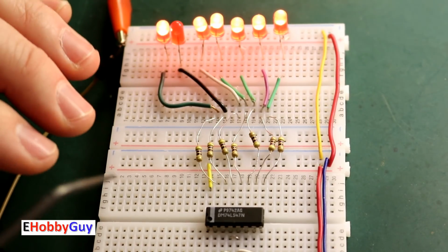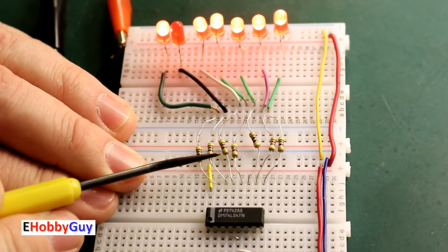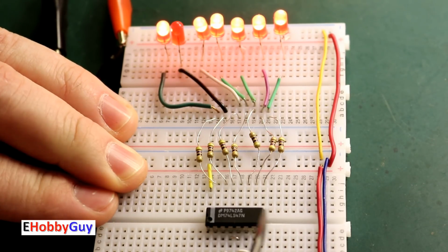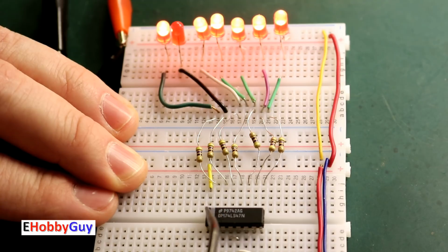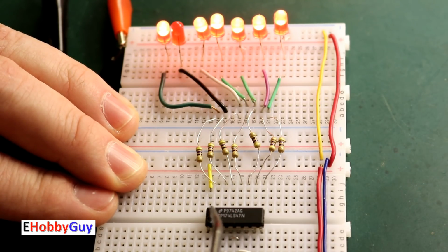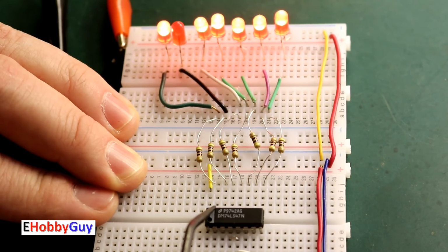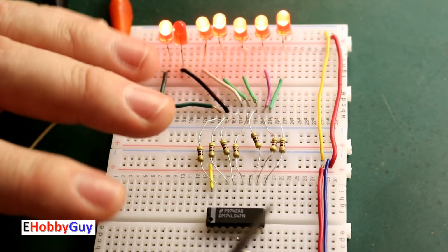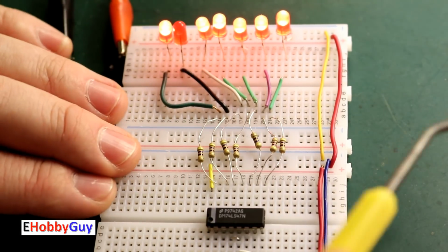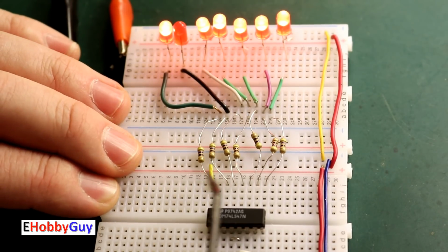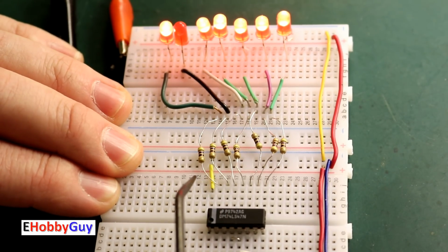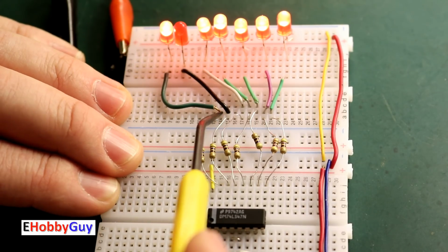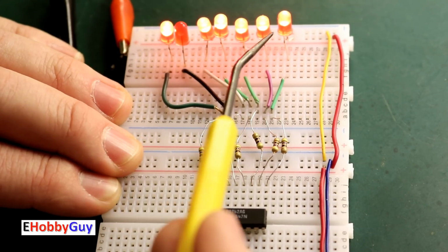Now looking at the outputs. For clarity, I just wanted everything to be nice and parallel, because the pins, as we looked at a little earlier, start at this pin right here, which you can't really see, but it's the 4th pin down, 16, 15, 14, 13. It goes A, B, C, D, E, and then comes to the 15 pin F, and then G. They would be jumping over each other, and it may make it a little confusing. And so what I did, just for clarity, is I brought these current limiting resistors up to the board here so that it could light the LEDs right here.